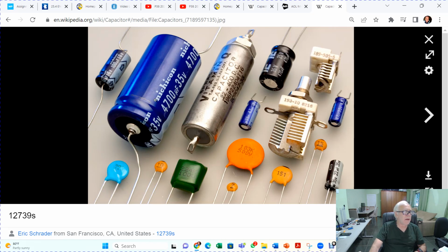This one here has a larger capacitance, 4700 microfarad, with a maximum voltage that can hold the charges, otherwise the capacitor starts to ionize the dielectric around it, at 35 volts and so on. Let us calculate the maximum potential energy that this large blue capacitor can store.